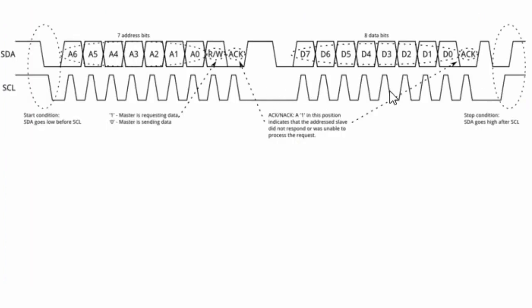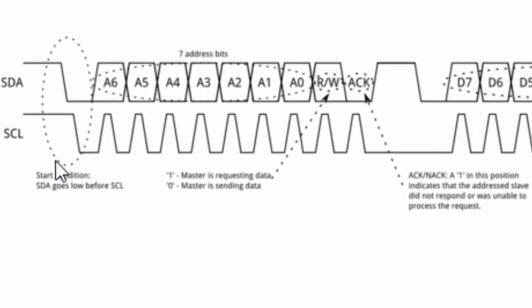This diagram shows the I2C bus operation. As this is a synchronous serial communication, a clock signal is necessary to synchronize the operation of both devices. It's always generated by the master device and its frequency directly affects the baud rate. When the master and the slave component are synchronized by the clock, every data exchange is always initiated by the master. So when you enable the MSSP module, which is Master Synchronous Serial Peripheral, it waits for the start condition to occur.